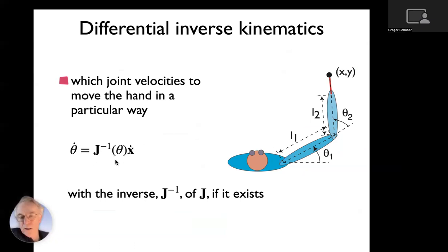You actually know your current joint configuration at any moment in time. And this tells you what joint velocity you need to realize a certain end effector velocity. So in motion planning, you would say, I make a path for my hand to the target, and at every moment in time, that path creates a velocity of the hand in space, like three-dimensional, also rotational, if you want to control the orientation. And then I can compute what joint velocity vectors I need, and your servo motors mounted on the robot arm can realize or control these joint velocities.